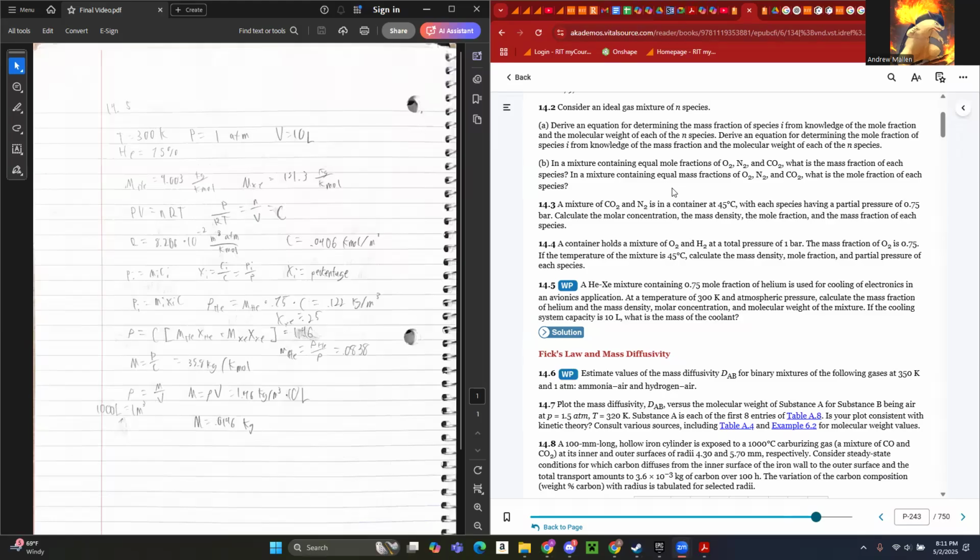Hello, everyone. In this video, I'm going to be going over problem 5 of chapter 14 in the Fundamentals of Mass and Heat Transfer textbook. This problem states that a helium and xenon mixture containing 0.75 mole fraction of helium is used for cooling of electronics in an avionics application at a temperature of 300 Kelvin and atmospheric pressure. We want to calculate the mass fraction of helium and the mass density, molar concentration, and molecular weight of the mixture. If the cooling system capacity is 10 liters, what is the mass of the coolant?